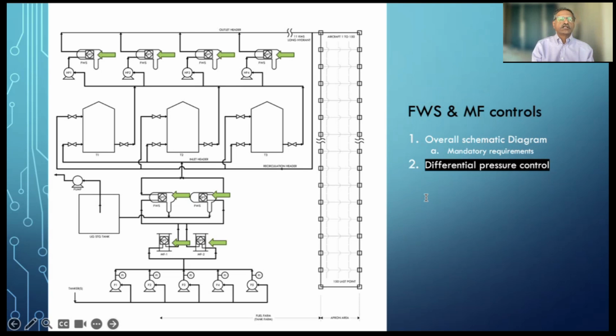Then next is filter water separators, because you have to also eliminate entire moisture or water. Even a small droplet is not acceptable. So you remove complete dirt, complete sedimentation, complete moisture or water content in the fuel. For that purpose, you have microfilters in the beginning itself, then you have filter water separators, and then when you are pumping the product out from the tanks, you again have filter water separators.